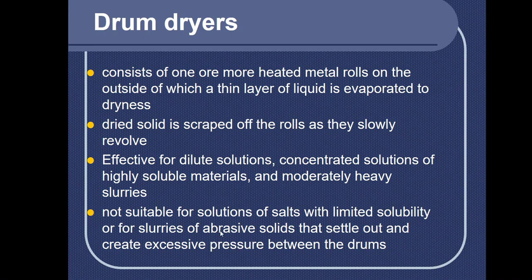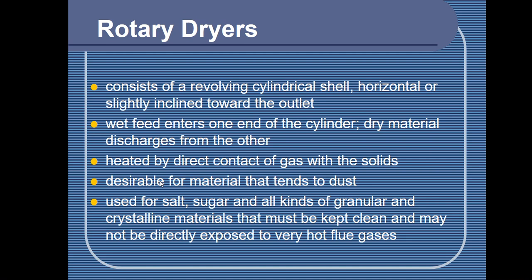Now, the drum dryer is not suitable for solutions of salts with limited solubility, and it's not suitable for slurries and abrasive solids. Take note of this. Now, let's look at the rotary. It is desirable for material that tends to dust and is used for salt, sugar, and all kinds of granular and crystalline materials.